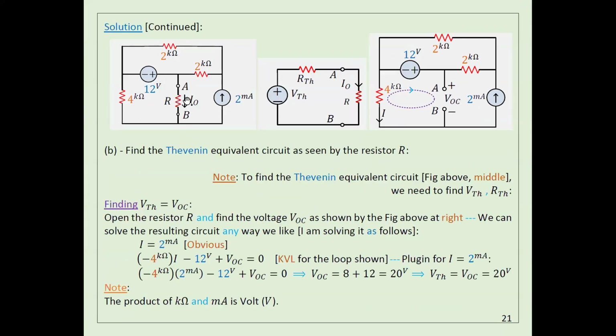So the first thing, as you see here, guys, this is the original circuit. So this should be the equivalent circuit, after I find R Thevenin and V Thevenin. So now I need to find these two. Once I find these two, it will be easy to calculate I0, given 3 values for R. It will be much easier than chapter 3 using the approaches we explained in chapter 4.